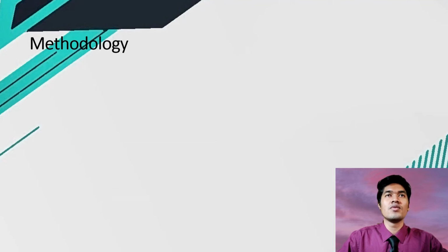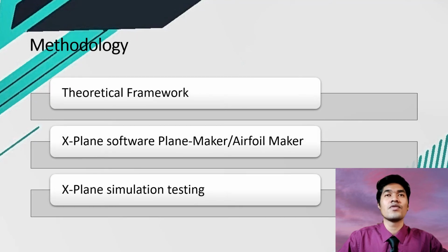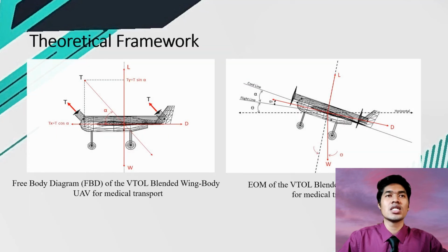The methodology that will be used is the theoretical framework, X-Plane software, Plane Maker and Airfoil Maker, and X-Plane simulation testing. For the theoretical framework, the data such as the free body diagram, equation of motion, coefficient of lift, thrust and motor, propeller thrust, and angle of the thrust will be computed using the theoretical framework.